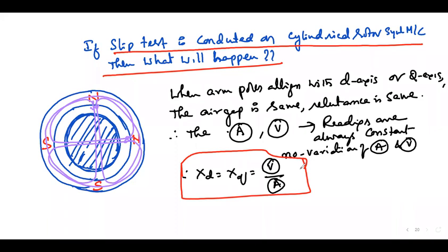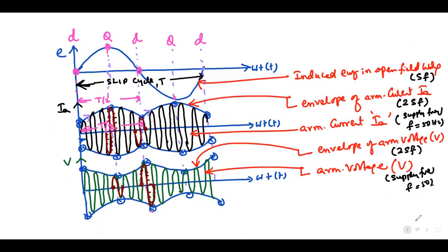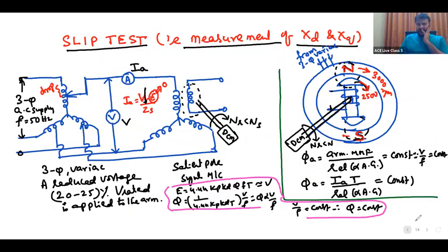One doubt: when we supply the field current, if NR is greater than NS, then power will flow from the DC to the AC side. Let's suppose it is driven by some motor. If you are rotating at more than synchronous speed, it acts like a generator. Whatever you are saying, that is power flow from the DC side to the AC side, no? Yeah, that is okay.